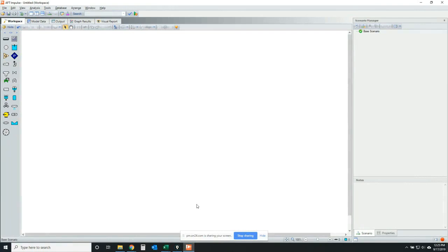So where do you start from here when you want to build a model of a valve closure example? Well, the best thing to do is to follow the yellow brick road, which is the little red status light in the bottom corner of the interface. This will allow you to go through and figure out what steps you need to complete so that you can do your Waterhammer analysis. The first item is already completed. The next thing that needs to be done is to specify the system properties. That's simply the fluid information.